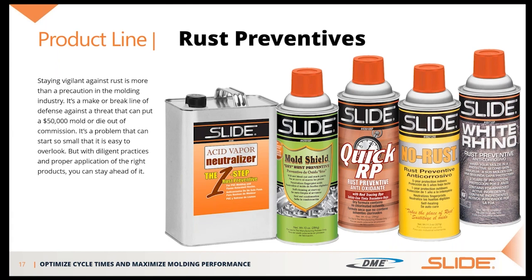That green can there, the mold shield, is a dry rust preventive. It's a 2-year. This product is awesome because it saves you time and money by the fact that it just flashes off, so you don't have to clean it before putting it back on the press and starting production again.